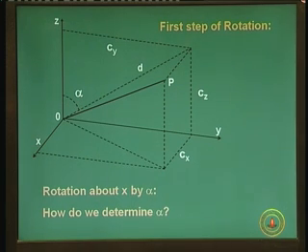Now, you see I have projected the axis OP onto the zy plane, and Cx, Cy, Cz are nothing but the direction cosines. So, assume that OP is a unit vector in length, and the corresponding coordinate projections are Cx, Cy, Cz respectively, which are nothing but the direction cosines, and D is the diagonal, or the length of the projection of OP on the zy plane.